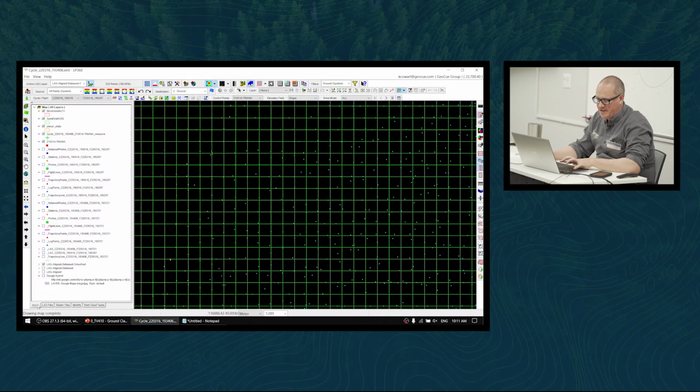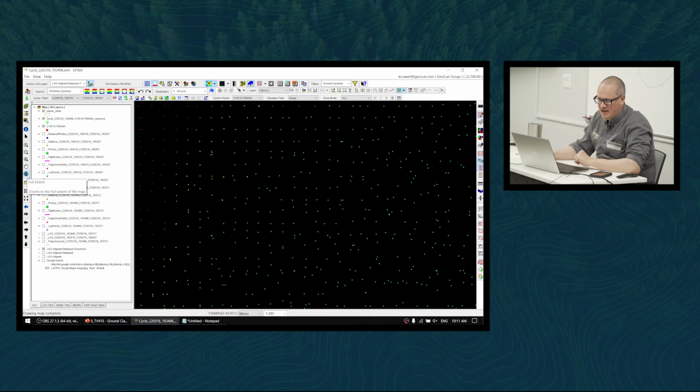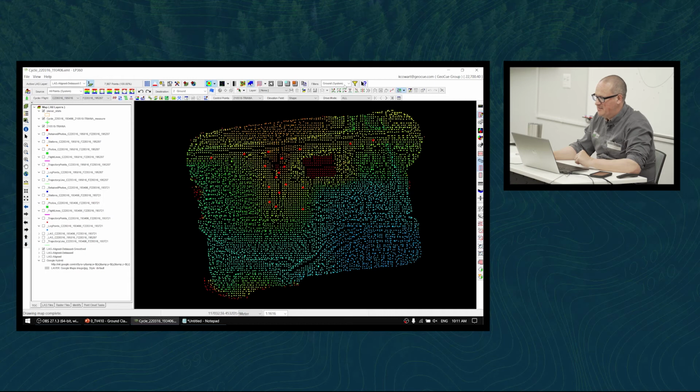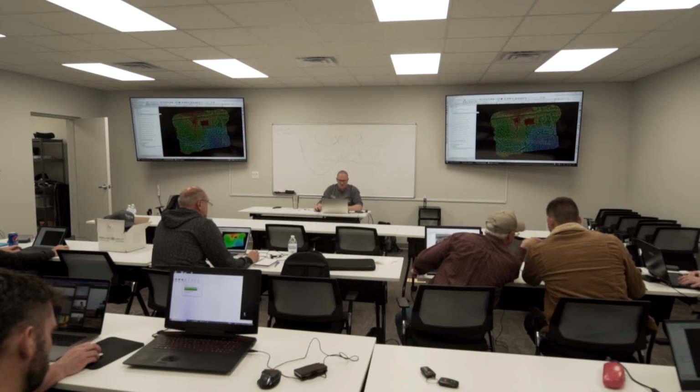I'm going to go back over to the table of contents. You should have 2 shapefiles in here for block seeds and seed grid. I'm just going to control select those 2, right click and delete. We don't need those yet. I should have showed you some of these navigation tools, but we do. If you look at this little globe one over here, this is zoom to full extent. So if you click that at any time, it'll zoom back to your full map. I'm going to turn my control points off too. We don't need those at this point.